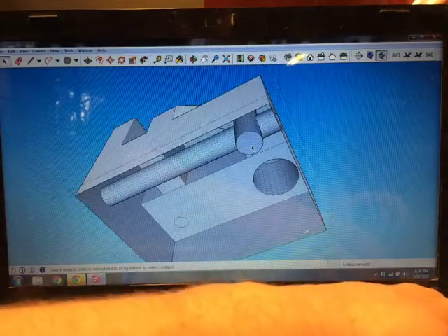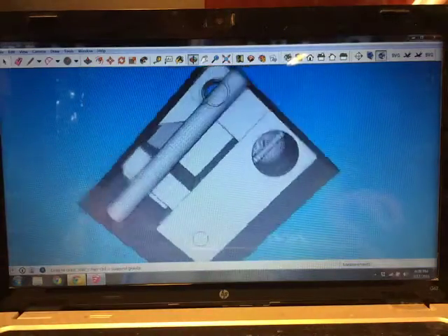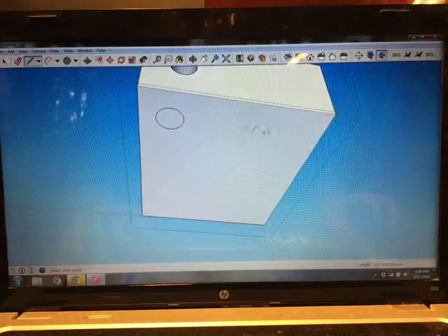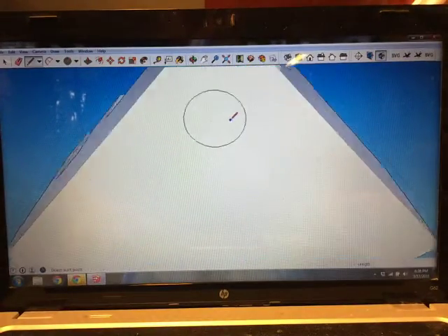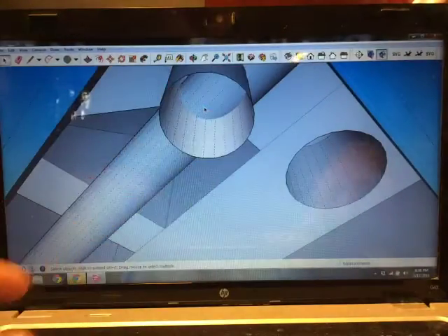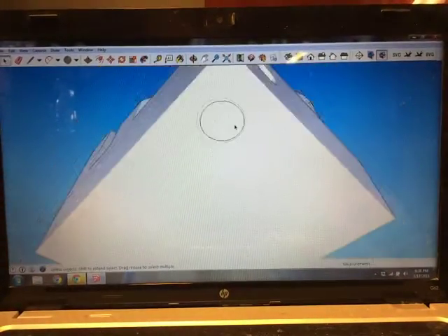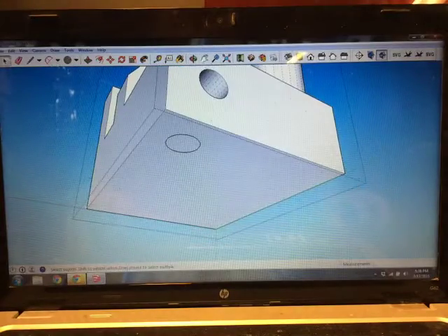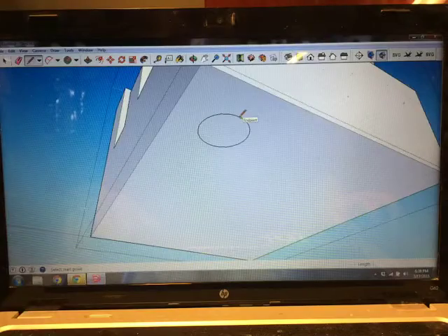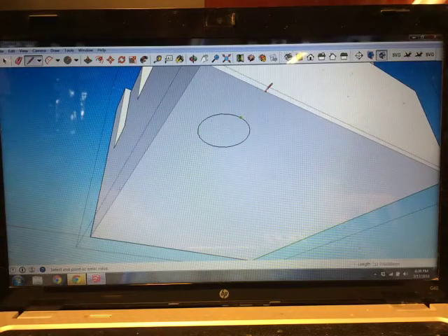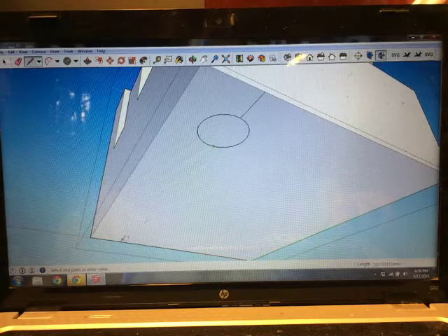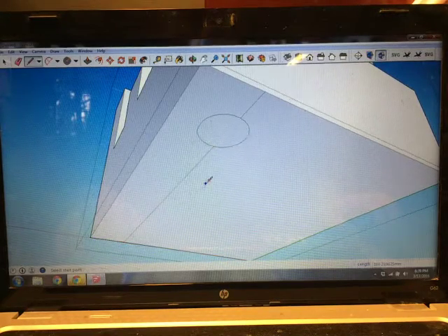Well, okay, we can redraw that. Let's delete this, and then let's go ahead and redraw the side. Should be good. Well, now what's going on? If I select this, it selects the whole thing again, and then if I delete, it deletes the whole thing again. Well, it's because one of your corners is out of spec. There are ways to get around this if you don't want to keep everything perfect, and that's by remapping the bottom surface. So you could do that by drawing lines from their endpoints to the edges of that bottom surface.